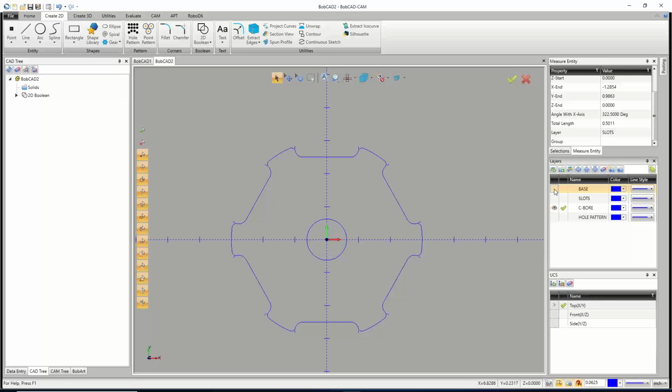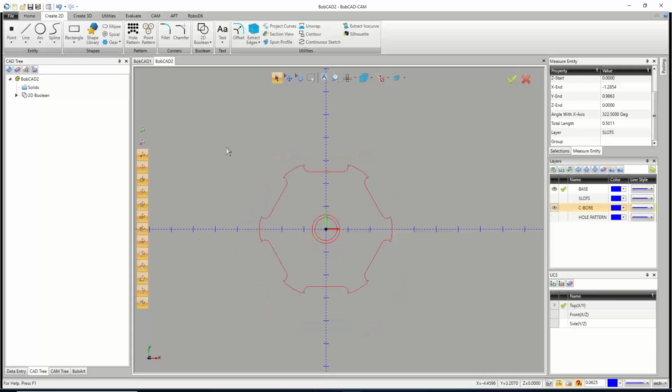Why is that disappearing? I switched layers at some point here. The base, oh, the base got moved. Okay, no big deal. So a really quick way of grabbing that geometry, what I do is grab the geometry you don't want first. So I'm just holding shift and clicking those. With arcs, you don't really have to hold shift, but shift click, grab the geometry you want, then drag a box over all the rest of the geometry, and it'll deselect your stuff from before, select all those mini lines, and then we just hit delete, and they disappear, and I now got clean geometry.